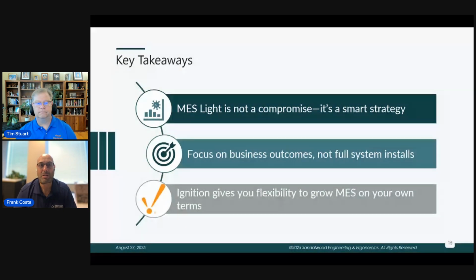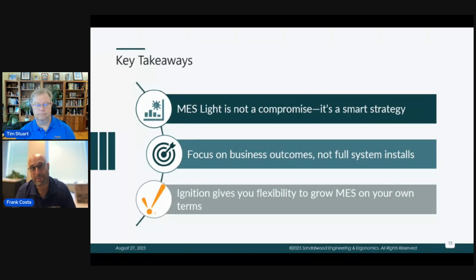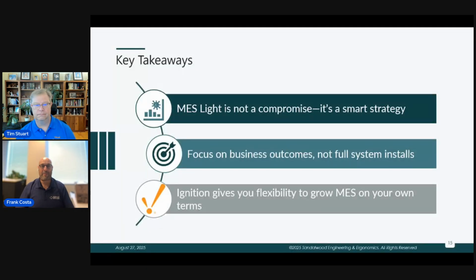When you get into the really, really old stuff, and if we're talking PLC 2, I've run into that before. PLC 5, right? There are some software packages specifically designed to consume data from those older systems and then output something more modern. We've gone through and done it with some of these pieces of equipment. I'll go to Anybus X. They've got little converters that'll take the information and spit it out as an MQTT message, Modbus TCP, and again, those are all consumable.